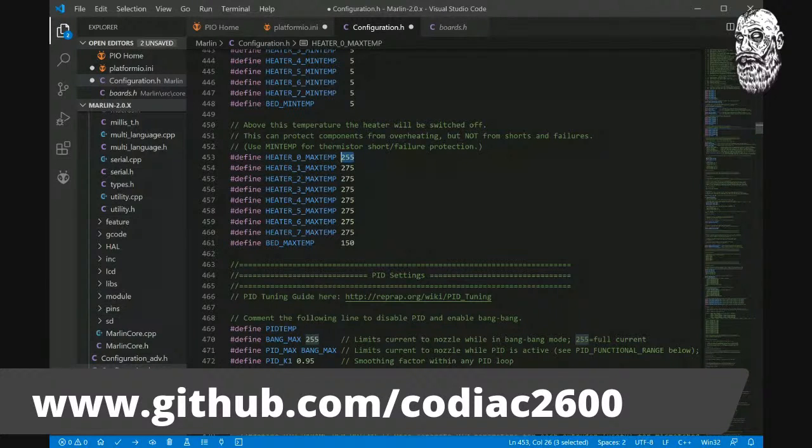And the stainless steel isn't good past like 350 C. So there's a big asterisk there. 300 C is typically safe, like if you're going to do nozzle changes and stuff. So typically we say 295 when we have an E3D V6, only because we need a safety buffer. There's like a 15-degree buffer. So our max heater temp, if we want to get to 280 C, we need to say 295. You can also write 295 plus 15, and that's just a buffer. So we'll just write the 15-degree max buffer thing.